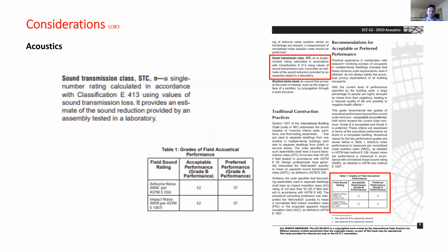So continuing with the acoustics, we're going to dive into the IBC specifications for sound isolation. These standards ensure that our designs not only look good, but sound good too, or don't sound good if that's the goal of your program. An interesting aspect here is the role of the materials in sound absorption. Thicker materials often provide better sound isolation, which is a crucial consideration in designing spaces, especially recording studios or private offices.